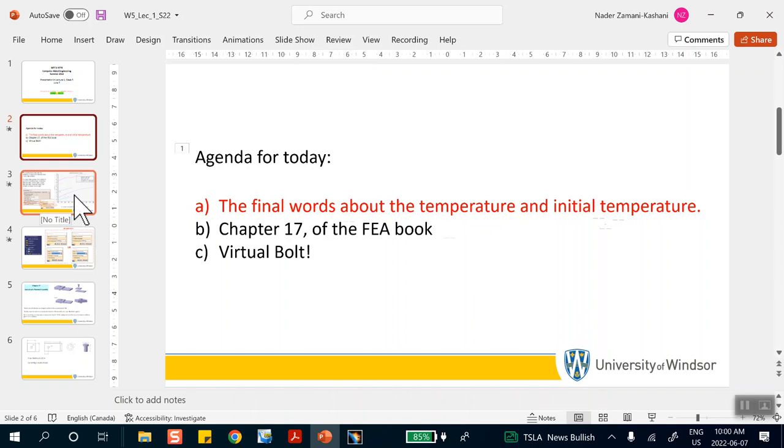Let me put it this way. When you say, okay, use the default properties, for example, steel or aluminum or some material in CATIA, you can go find out what the numbers are. For example, you click on the material, steel or aluminum, and then the analysis tab, it gives you the Young's modulus in the units that you have, Poisson ratio, coefficient of thermal expansion, and there is a density, and at the end it gives you the yield strength of the material. Total nonsense, totally useless, because CATIA does only linear elastic material.